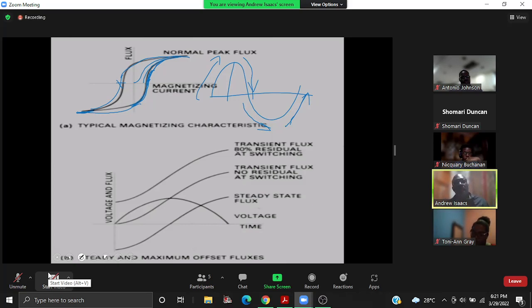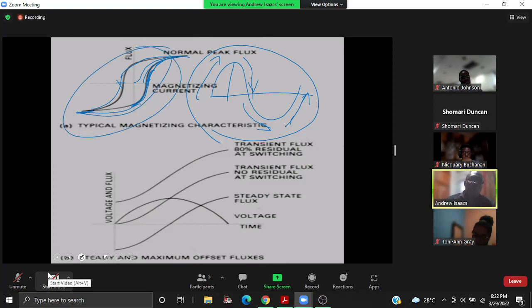Now, what we are saying in showing this is that that magnetic cycle has to occur within the core before you start seeing an output. But to do this, you require input. And that's the magnetic inrush, because it is coming into the transformer for the sole purpose of creating the magnetism. All right?